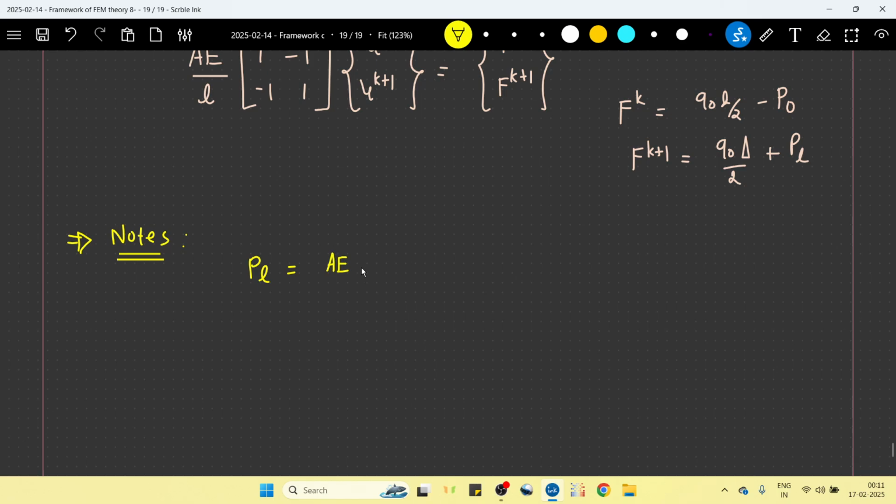So this is before weak form. We have written this a u dash at x equal to L, and P0 is equal to a u dash at x equal to 0. Okay, and a u dash is nothing but a du by dx. So it stands for axial force in the bar.